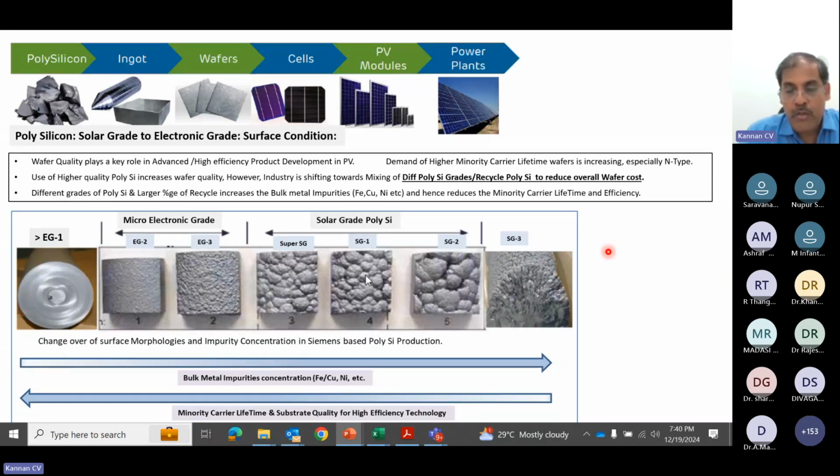So you don't need to use the same kind of polysilicon for both applications. For semiconductor applications, the growth speed is different, so that they can grow very high purity polysilicon raw material, 11N, 12N purity, whereas for solar, whether it's the CZ process or the DSS multicrystalline process we discussed yesterday, you may not need 11N purity.